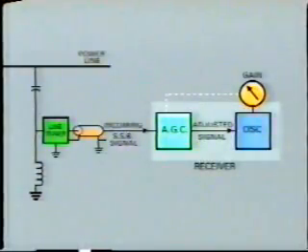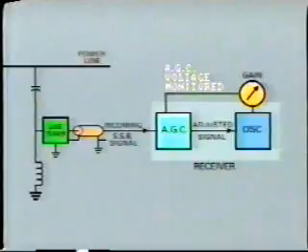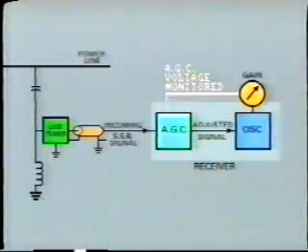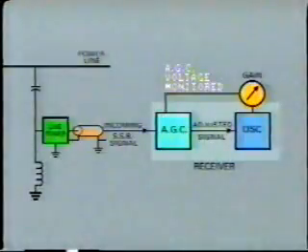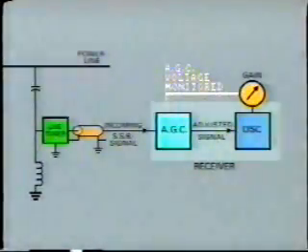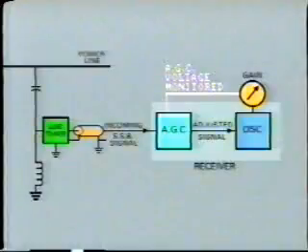Conversely, if the signal becomes weak, the AGC turns the gain up. The magnitude of the AGC voltage signal provides a useful indication of the quality of our power line carrier channel. If the gain is high, we must be receiving a weak signal, and vice versa.